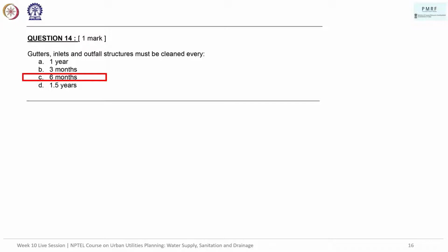It's not just about having gutters or inlets and outfall structures, but it's also about the topography of the city, which has not really been respected when we are constructing. Essentially, we have encroachments on depressions that were previously ponds. Those areas are going to continuously run into trouble. It's not just about filling in land and keeping the structure taller, but looking at the general scheme of things, take the entire city and its topography.